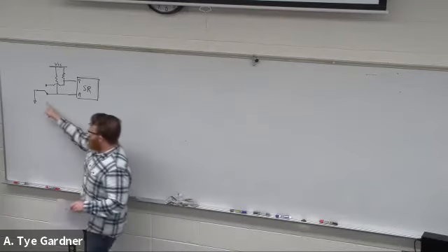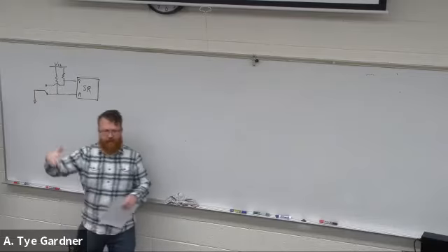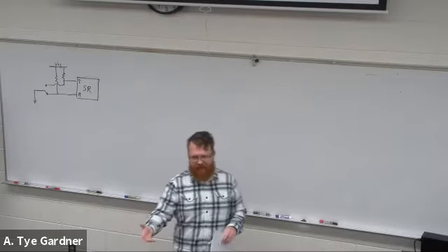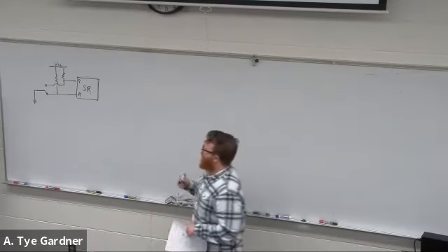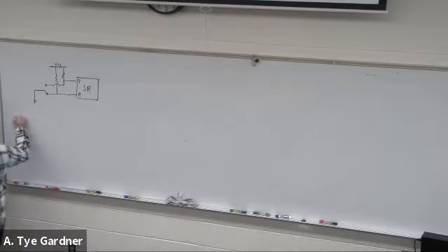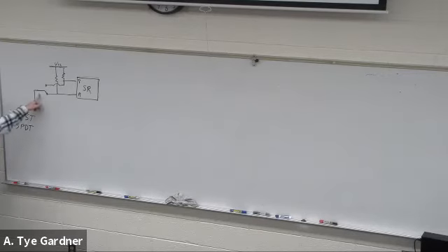So this is my button. Instead of having just a contact or no contact, now I have to have what's called a single pole double throw. So let's introduce some switch terminology. Single pole, single throw. This is what your push buttons are. It is either disconnected or connected. That's all it does. Whereas single pole double throw is this. There is one input, and two locations that it can go to.